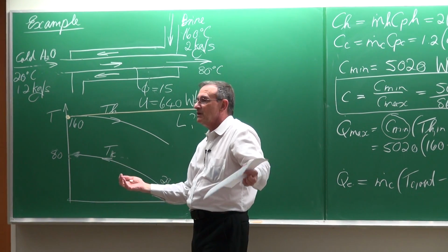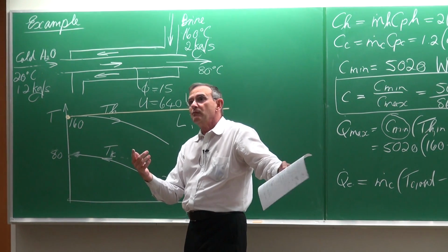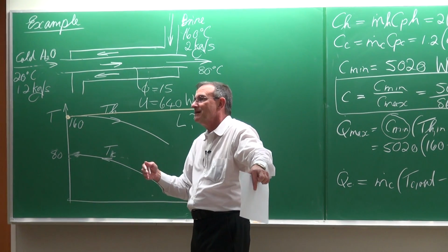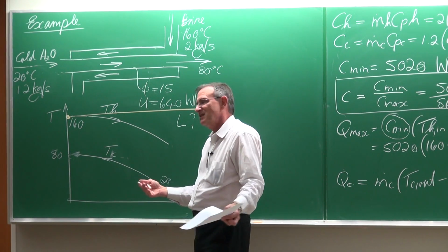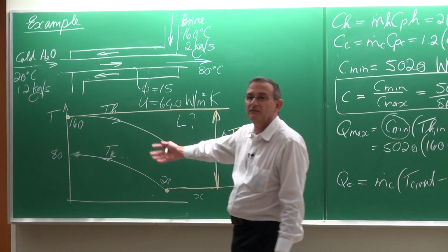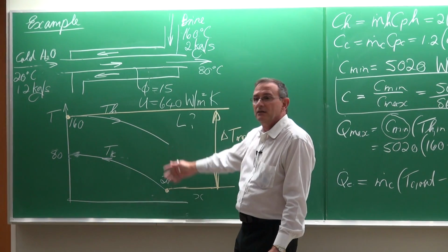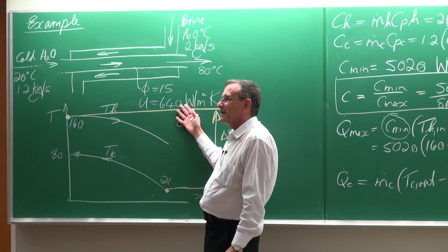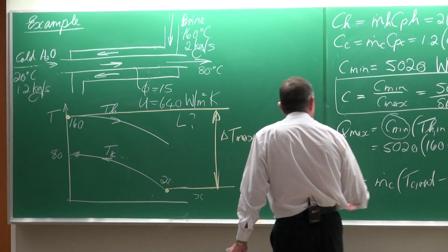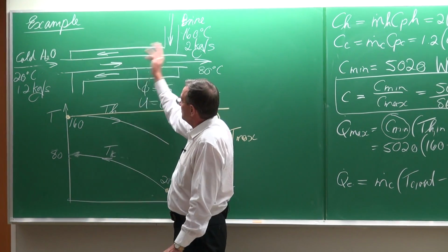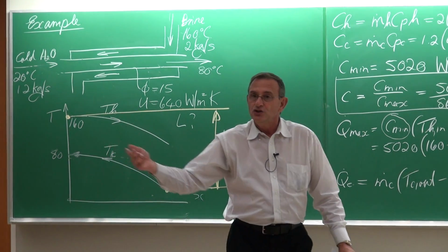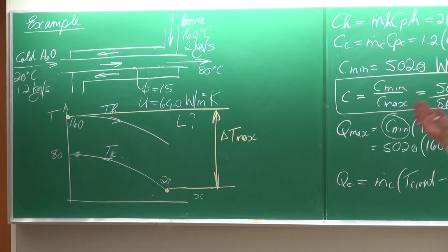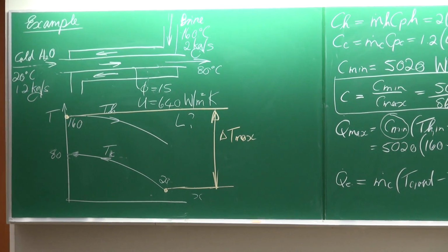It is an uncomfortable thing. If you must get it into this building, 108 meters, you can't bend it. Obviously, you can get it in while you're busy with construction. You can put it in, but if you need to replace it, it's a very long thing, not something very nice to work with. So typically, these types of lengths would obviously not be practical if you want this type of heat transfer with these types of inlet temperatures and mass flow rates. You'd rather go for a shell and tube heat exchanger or a plate heat exchanger, which will be much more compact. Okay. Let's do a second example.